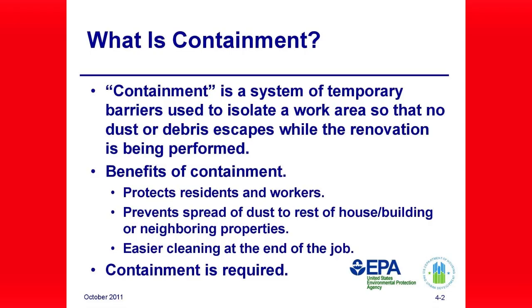Facilitate sufficient cleaning of the work area. The work setup process is essential to keeping lead-contaminated dust confined to the work area where it can be easily cleaned. Proper containment of the work area helps to limit the area you need to clean after the job is complete. Knowing exactly what to clean is an important factor in saving time and money spent on a cleanup.